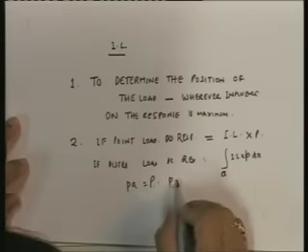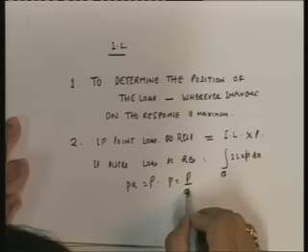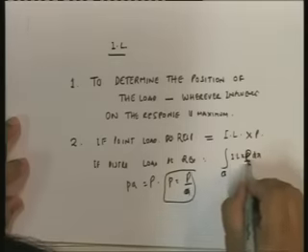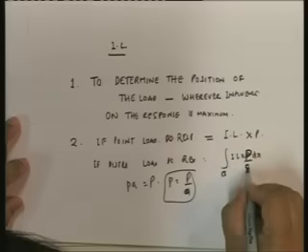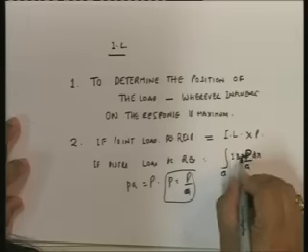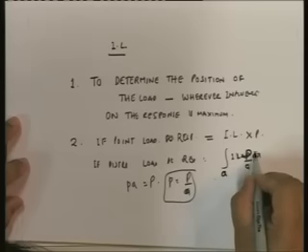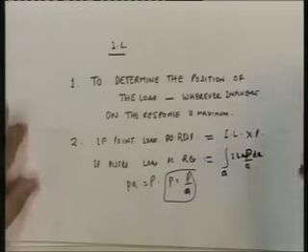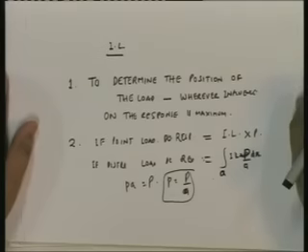So basically the pressure p is equal to P upon A. And so therefore here what we do is load upon A multiplied by the influence line over the length A, you integrate it. Okay, and that gives you the design response. So this in essence is what overall this thing is.